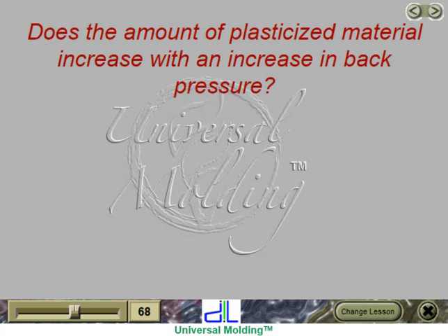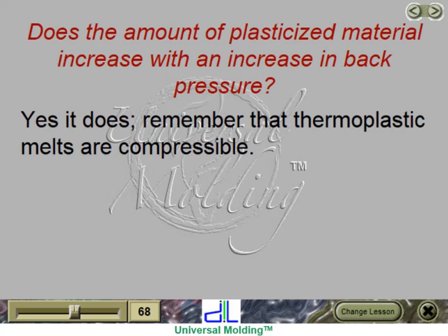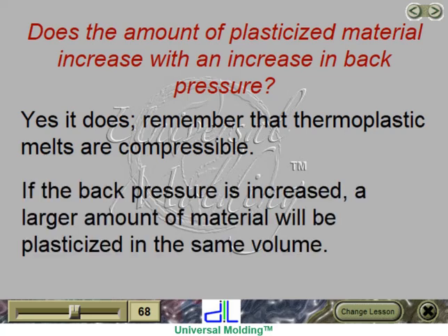Does the amount of plasticized material increase with an increase in back pressure? Yes, it does. Remember that thermoplastic melts are compressible. If the back pressure is increased, a larger amount of material will be plasticized in the same volume.